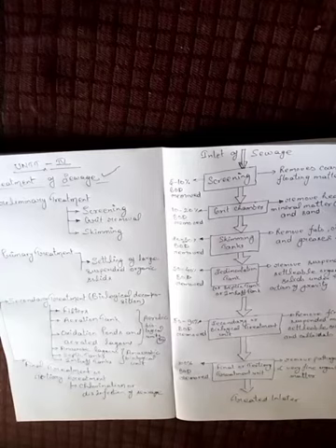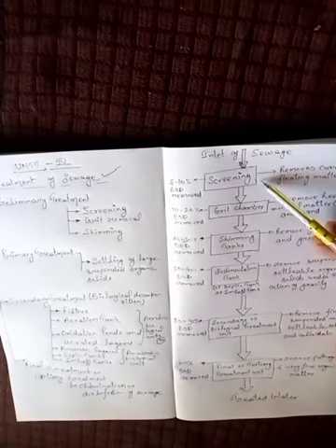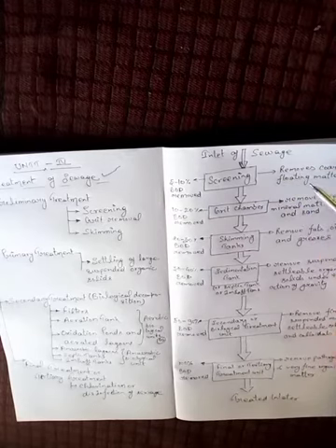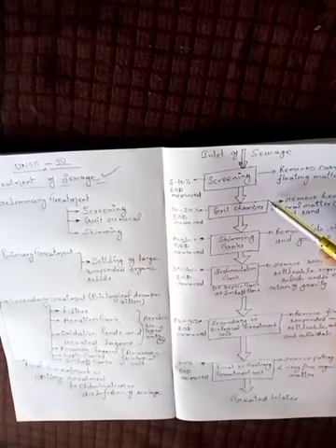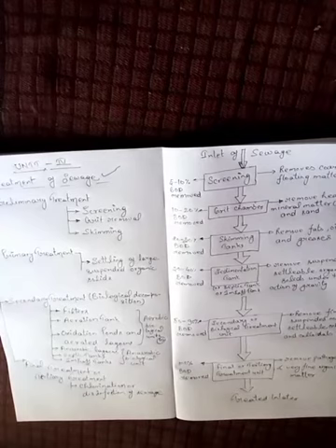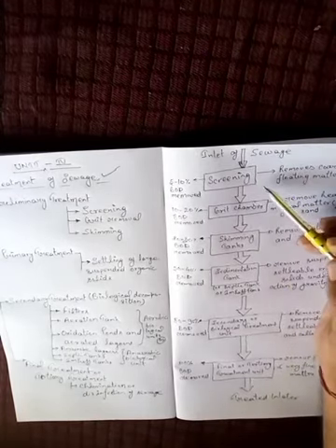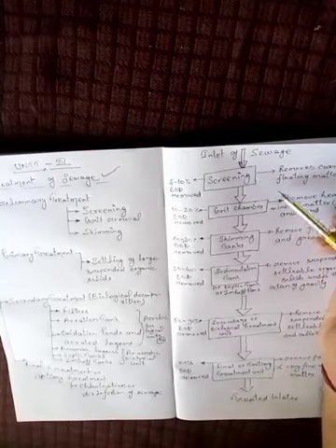Here I have shown you a specific flowchart of a treatment unit. Here is the inlet of the sewage. After that, the first step is screening, which is the preliminary treatment of the sewage. You can use screens after the grit chamber, based on the quality of the sewage. If organic matters are low in size, then you can use screens after the grit chamber. But basically, screening is the first operation in the treatment system.